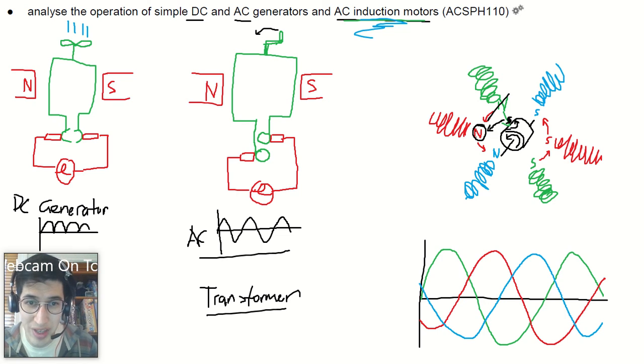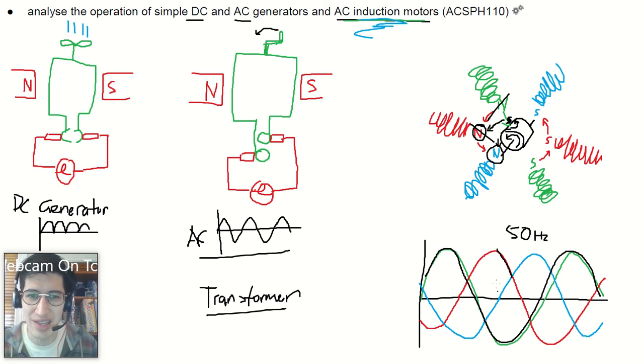What happens when this north here starts to disappear? At this point down here, that north disappears, this north appears, the south now follows that north pole, and so on. So it's going to spin to follow the spinning magnetic field. How fast it spins depends on how quickly these go up and down. And remember, for normal usage in Australia, this stuff moves at about 50 hertz. So it goes up and down at 50 hertz. That's going to dictate the speed at which your motor spins.